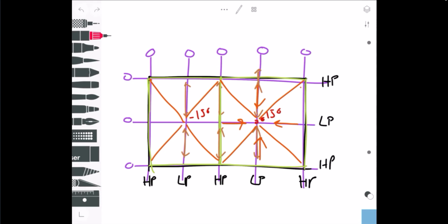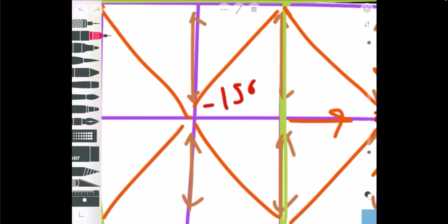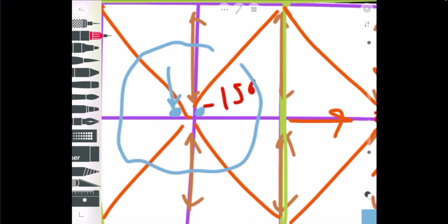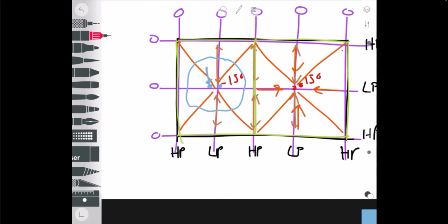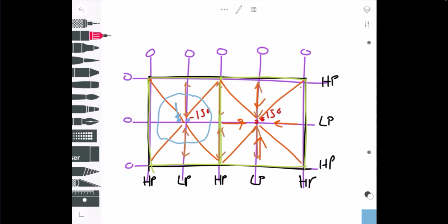So there are other options where you can do a secondary roof drain system. So there's one roof drain. You could have another roof drain right near it, but that roof drain has a wall around it. So it's not used all the time because there's a barrier around the roof drain of a certain height. That height would be 150 millimeters probably. So it would allow the water to pool to a certain point, and at a certain depth, it'll start going into that secondary drain. And then mechanical takes it over from there. But there is the option to do a secondary drain system as opposed to the emergency overflow scupper.